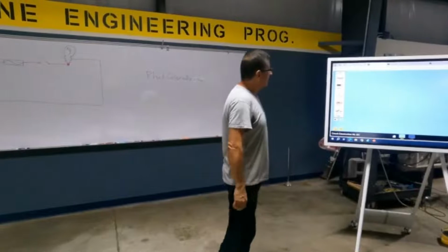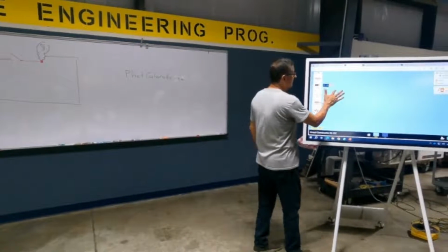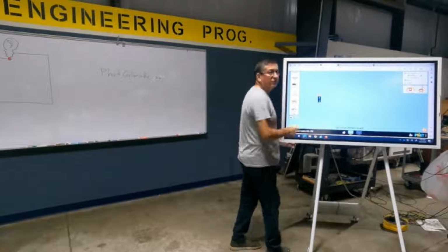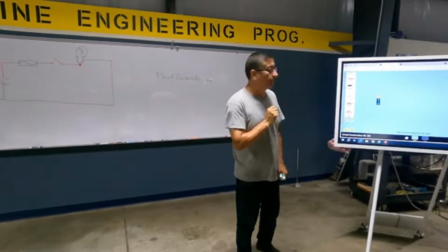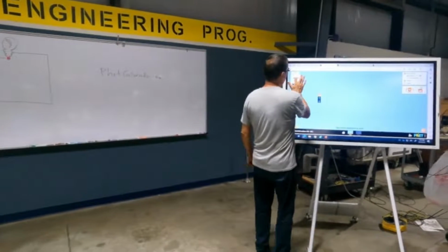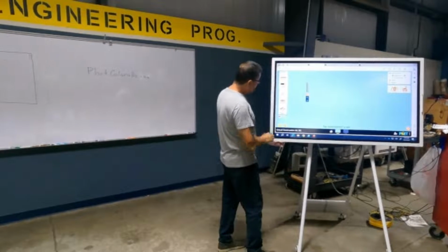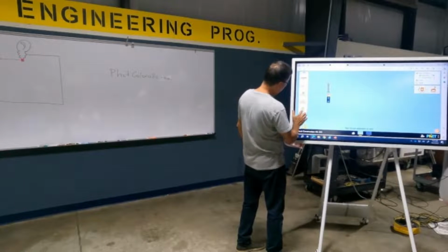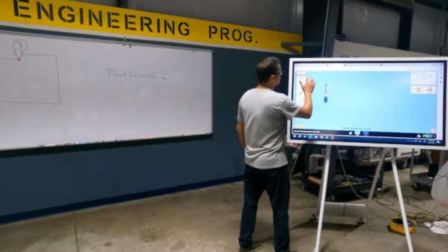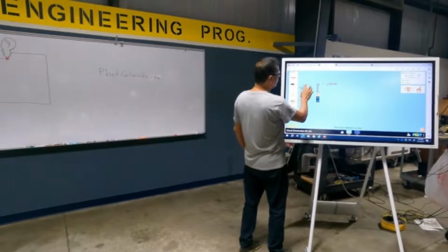If not, I don't have power in any part of the boat. Good? Okay, I am going to create one circuit here. Look, it's nice. The battery. This particular battery is 9 volts. I am going to make that circuit. I am going to connect wire number 1. After that, I am going to install a fuse. After that, another wire. After that, the switch.